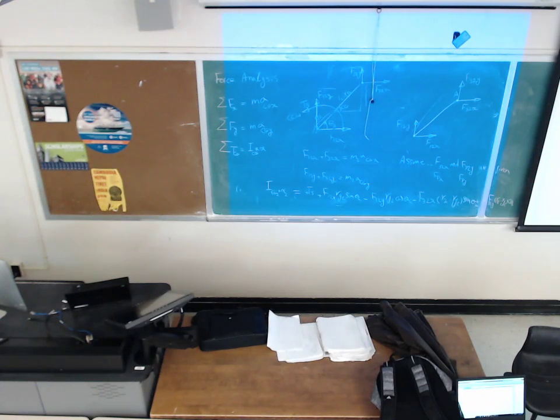Acceleration x double dot of center of gravity of 2. I differentiate one more time. I should differentiate the first term. A is constant, so I'll keep it there. Negative A theta double dot 2 sine of theta 2. Now I'm gonna differentiate this. Negative A theta dot 2 squared, because if I differentiate this, theta dot 2 is coming out, multiplied by this, it's gonna be squared, cosine of theta 2.